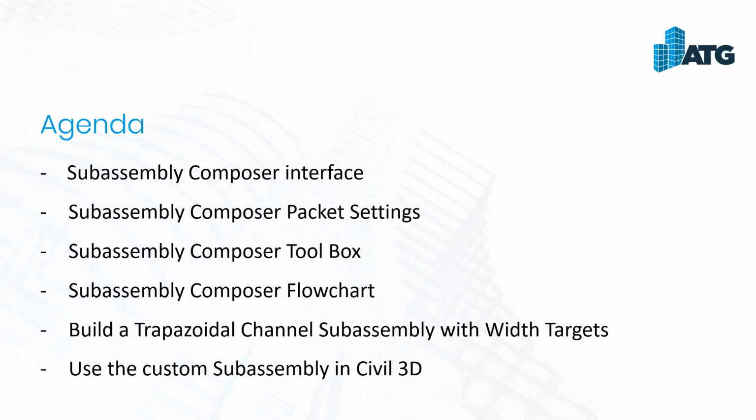Then we'll show you the Subassembly Composer toolbox, which is where all the tools sit. After that, we'll get into the Subassembly Composer flowchart, which is where we start to drag and drop to create our subassembly.